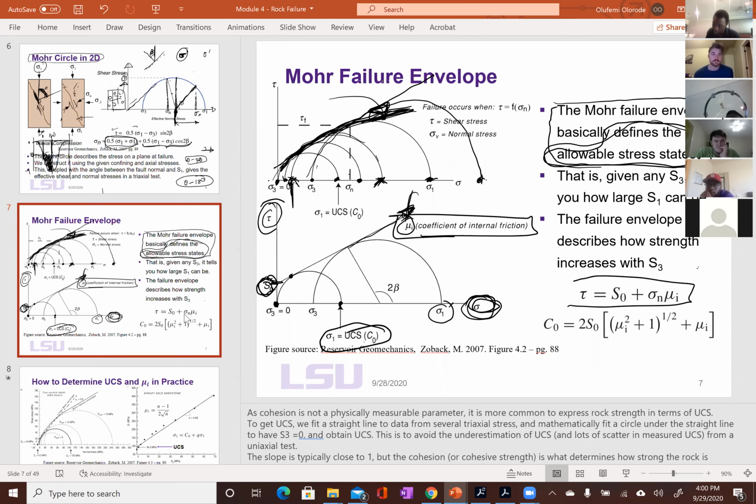And where I was getting at is the equation is very similar to this. The rock will slide or slip whenever the ratio of the shear stress parallel to the surface to the effective normal stress becomes equal to mu, and that mu is different from this mu. This is the coefficient of internal friction for an intact rock. So the rock is intact, no pre-existing fracture. And this one is the frictional coefficient of sliding. So it's mu without an i.